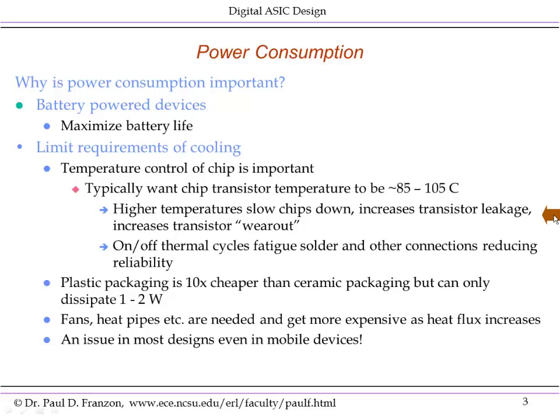What you might not be as familiar with is the problems of cooling for higher performance chips that are not constrained by battery power supplies, such as they're wall plug powered. Typically you want a chip to operate somewhere in the 85 to 105 degrees centigrade range. I'm not, of course, referring to the external environment. I'm not saying take your chips to Venus and operate them there.